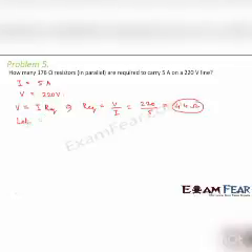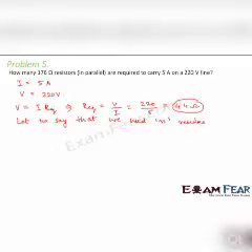Now let us say that we would need n resistors. So now we have to calculate the value of n. So if I say that I need n resistors to achieve an equivalent resistance of 44 ohms, what does that mean? That means that 1 by R equivalent will be equal to 1 by R1 plus 1 by R2 plus 1 by R3. How many times?